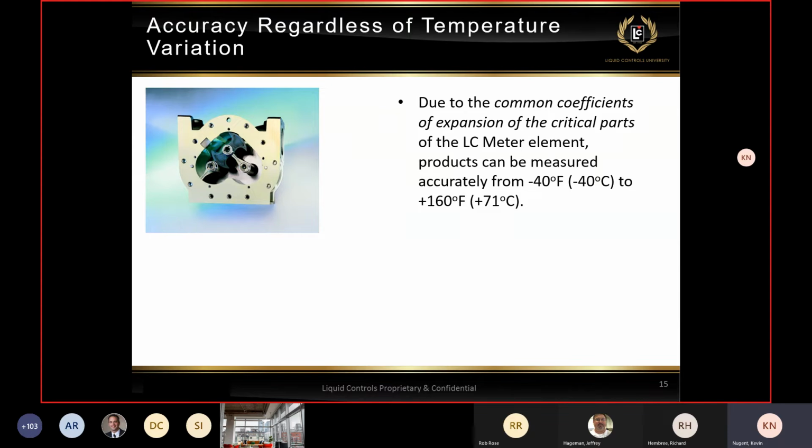In many cases, the meter's mounted outside if we're loading transports or rail cars. In some cases, the supply may be housed indoors, or since it's a large volume, it maintains a higher temperature. We definitely want to introduce the higher temperature liquid at a slower rate, since those internal parts have a very low clearance.